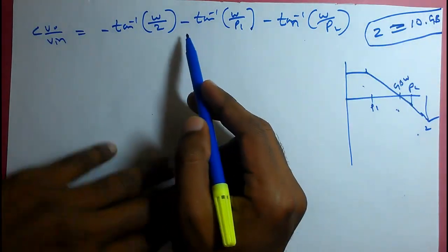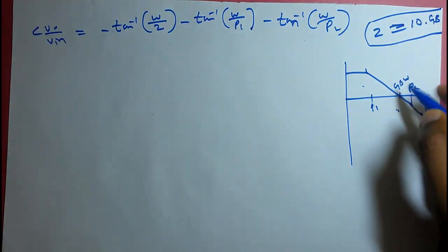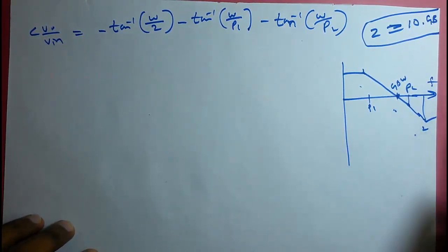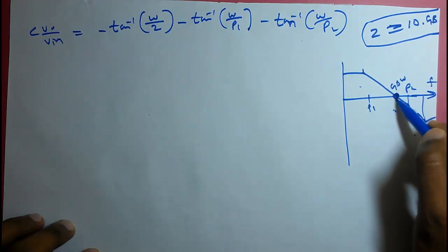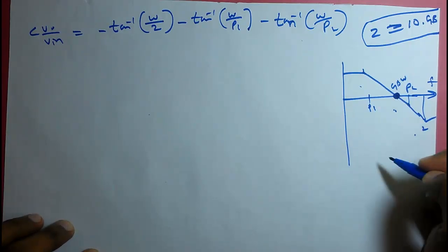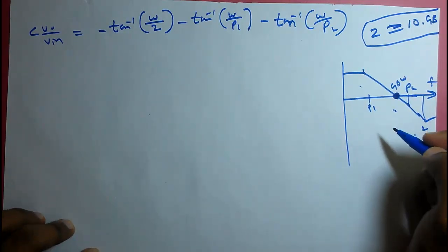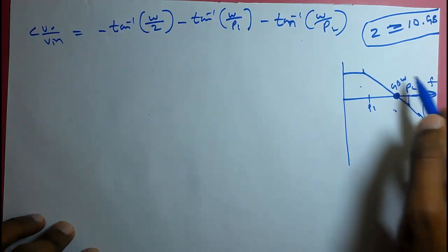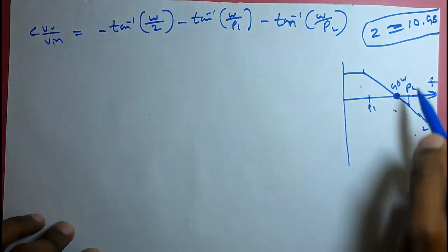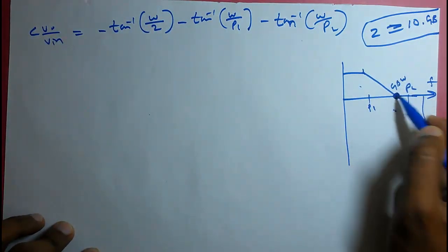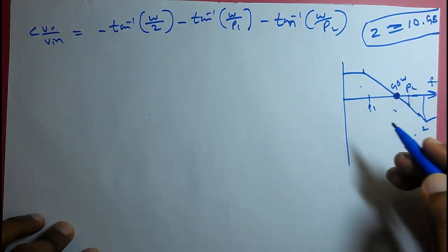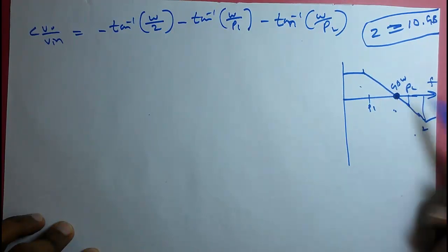So we can substitute these values here, and we are concentrating at this point. This is the frequency axis. When the frequency is equal to the gain bandwidth product or unity gain, what is the phase angle? That is what we are interested in. So we substitute omega with the gain bandwidth product, the unity frequency, because we have to find the phase at this frequency.